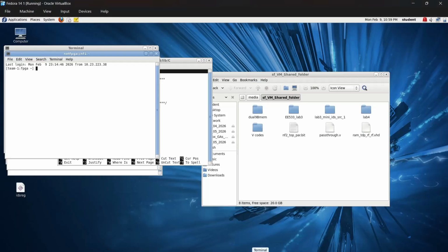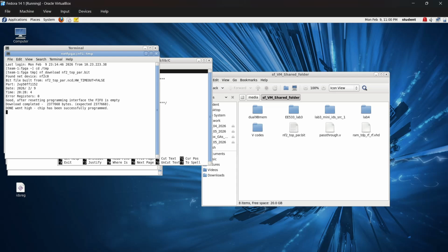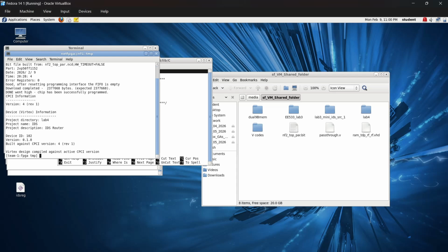So the final part of lab part 7, and the whole lab, is to implement our actual IDS project in the NetFPGA. For that, we have to import the netlist file we generated from synthesis. That file is called nf2_top, and I'll just download that first into the NetFPGA. So this is our final post-synthesis block, and we're just downloading it into the NetFPGA.